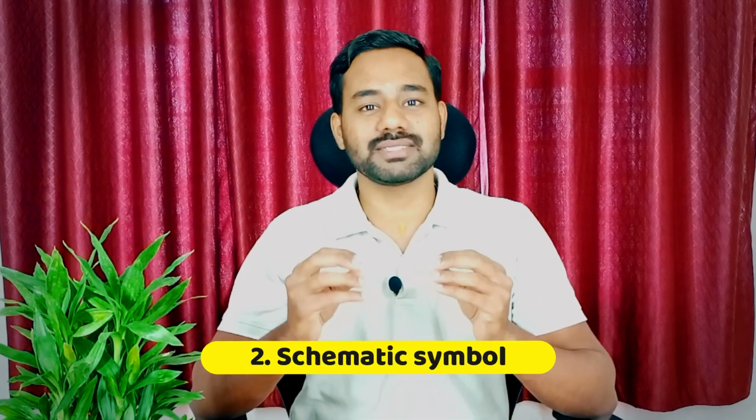Second part is understanding how to create a schematic symbol using EasyEDA, following the user perspective as well as the IEEE standard, not compromising on any electrical or mechanical details given in the datasheet, and making it more user friendly so that designers can use it in their comfort.